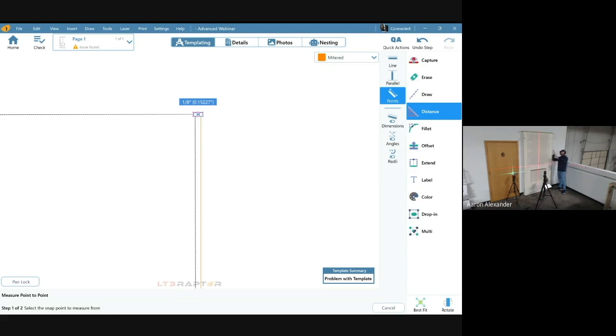And we always are going to install these returns plumb in space. So that is telling us now, and telling our installers even, how much they're going to have to shim the top there to get this plumb in space. And then we're obviously going to want to cut that on the face so we match that plumb in space when we go to put these layers together, right? So it's telling us right there an 1/8 inch.